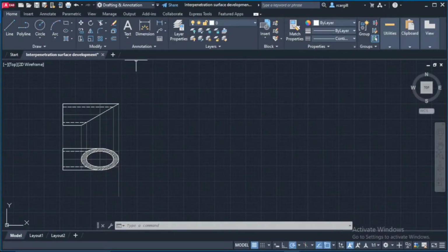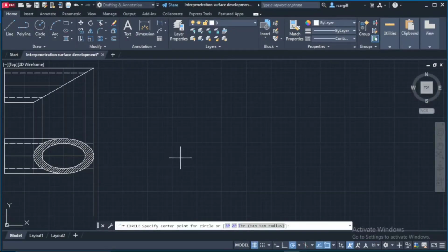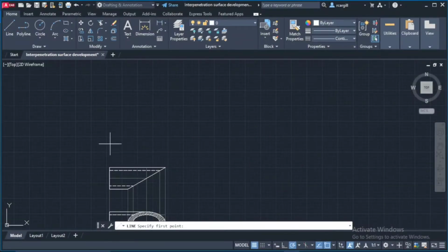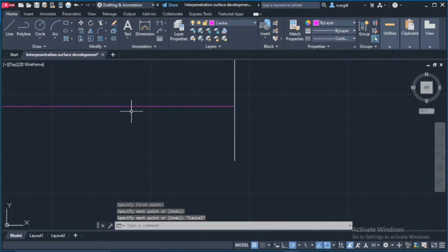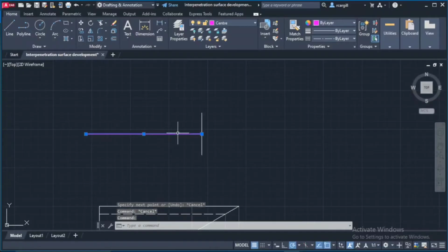And to draw the projection symbol, it is quite simple. In this case, I am doing a third angle orthographic projection. So I would just need a circle. Well, let me start with a line first. Start with the tube part. Let me draw it somewhere over here, above the plan view where it doesn't interfere with the drawing. So I would have a line like this, and then I would need a center line that would come across like this. Okay, my center, I need to change this to the center line layer. There we go, so that's my center line.